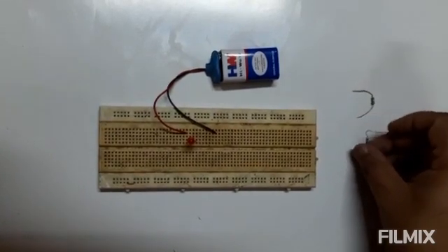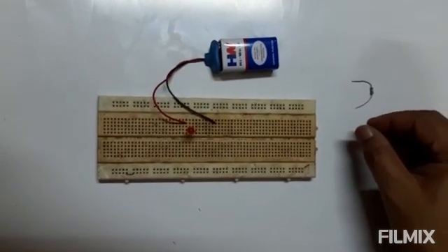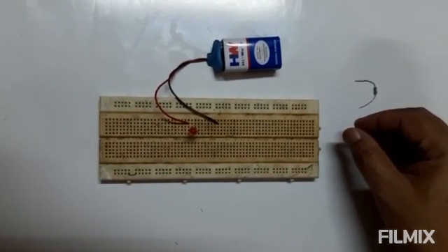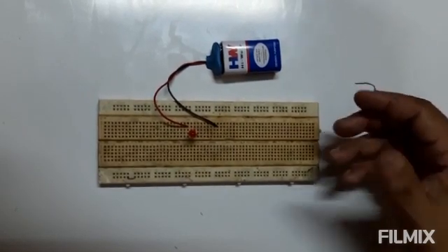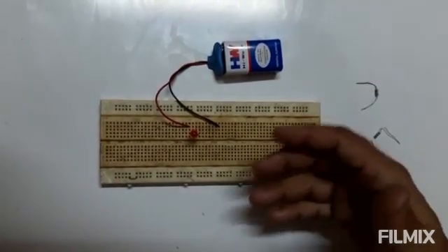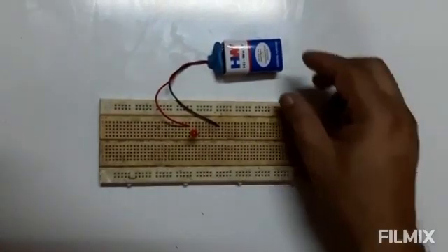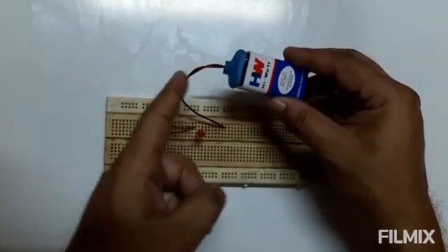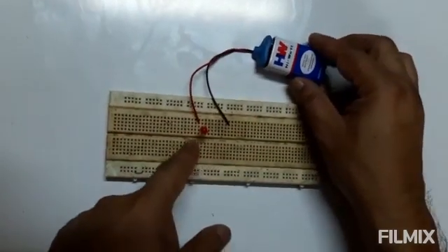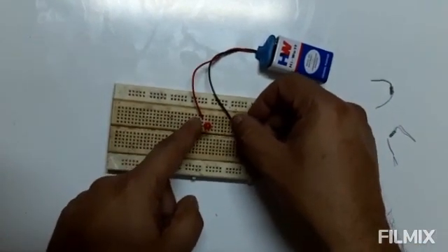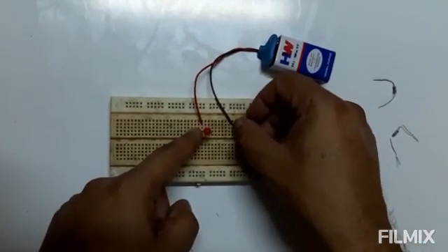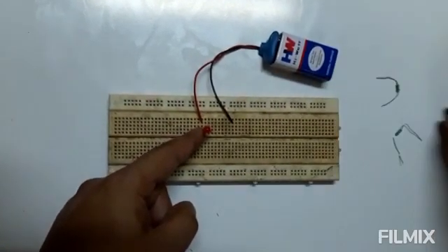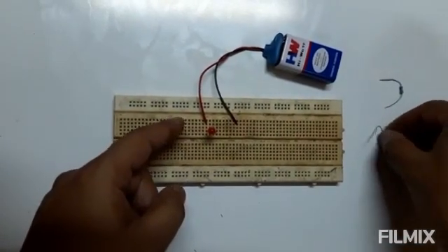I have explained to you Ohm's law, which is V equal to IR, and I've also shown you some components. Now I'm going to use these components to explain the theory that I've explained. This is a battery. It's a 9-volt battery. This is a battery strap, and I have taken the connections here. These interconnections are connected using wires inside. So now there's a light emitting diode, LED, and I'm going to use a resistance to connect them in series.